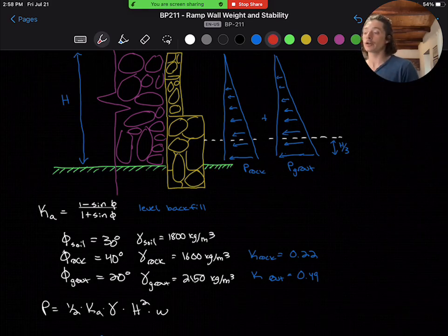In fact, approach ramps should be filled in 30 centimeter lifts according to the EIA Bridge Binder Volume 3 for field operations, with a maximum of 3 lifts, approximately 1 meter of height gained per day. And this is because of the following calculation.